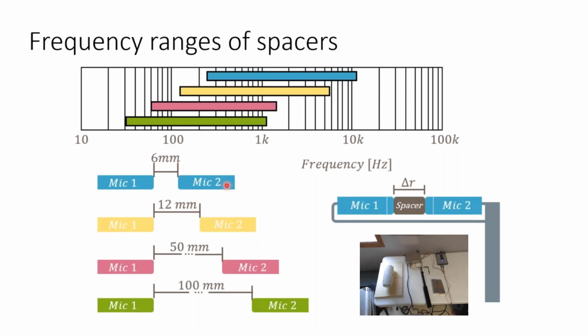that you're interested in. So this means you kind of have to have an idea of the sound range that you're looking for. So if you're doing high frequency gear measurements, you need to know that versus low frequency engine noise, because if you have the wrong spacer in, it won't pick those up. So here's kind of as you'll notice, the closer together those microphones are, the higher in frequency you can measure. So it's important that you kind of consult.